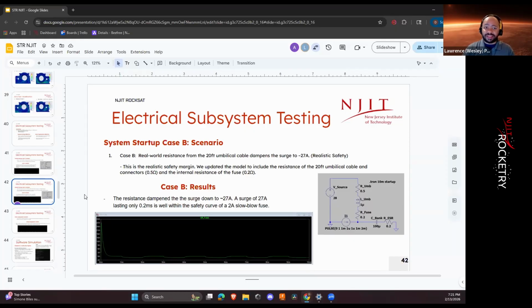So the EGSE will see that. It's not going to trip for you, though. I have those set a little higher than that. But yeah, that's an impressive amount of current for an impressively short amount of time. Just thought I'd point that out, but if you wanted to mitigate it, some inrush current limiting protection will ensure that you don't blow any of your fuses or Wallops. Well, you're not going to blow any Wallops fuses, but now I'm just talking too much.